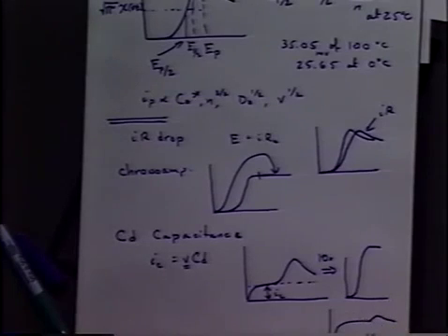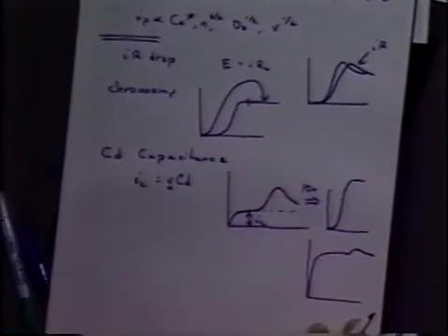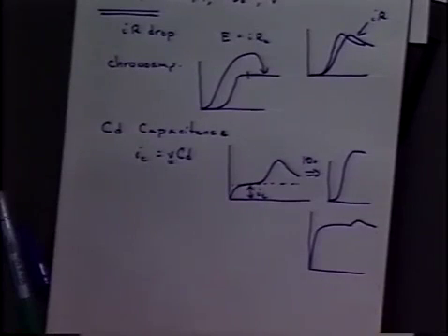And so our curve might look like that. And that's sometimes unacceptable. Pretty much all the time it's unacceptable. So not really much you can do to get around that. That's the fundamental thing. You can use smaller electrodes because the capacitance is proportional to the area of the electrode. So if you go to smaller electrodes, you can remove that effect.